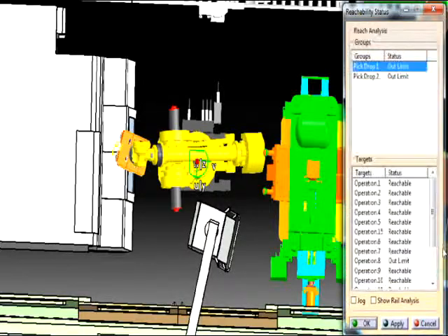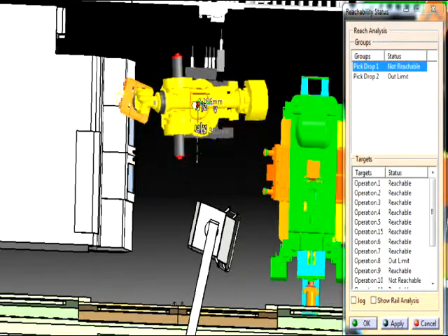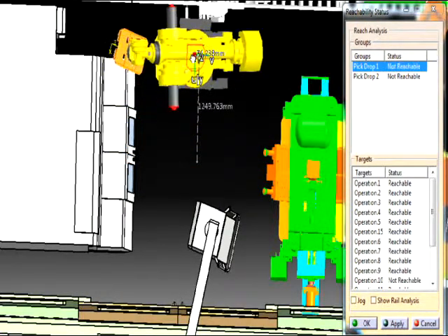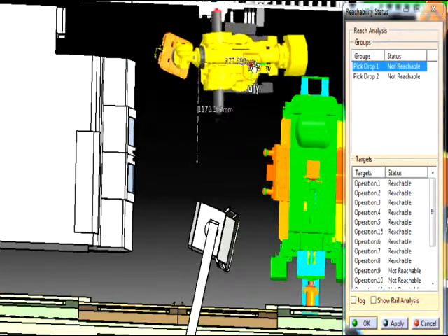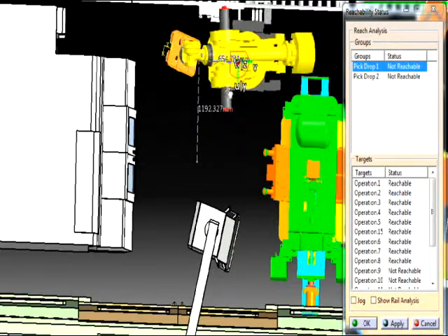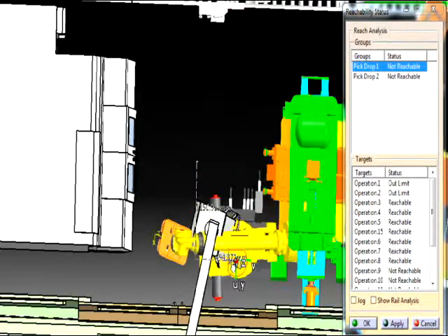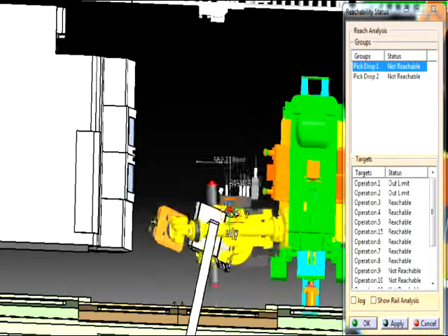Since robot processes are constantly being modified in the design phase, there's a lot of juggling of equipment and spot weld locations. Weld spots also tend to get traded from robot to robot, so it is important to be able to check all the robot locations for reachability quickly and easily.